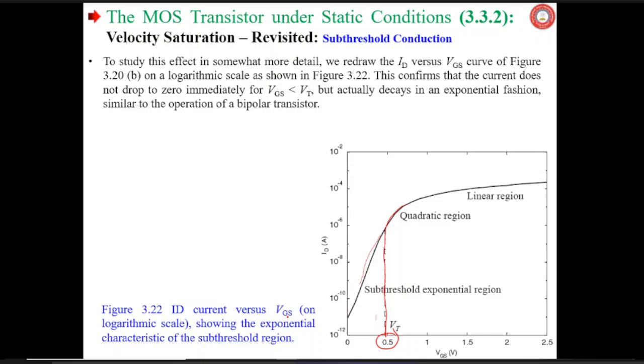For an ideal MOSFET, we have seen that the subthreshold slope is 60 millivolt per decade at 300 K or room temperature, and I_sub drops by a factor of 10 for a reduction of VGS of 60 millivolt. It means this only. For actual FETs, of course, it is 90 millivolt per decade, that is eta equals 1.5.